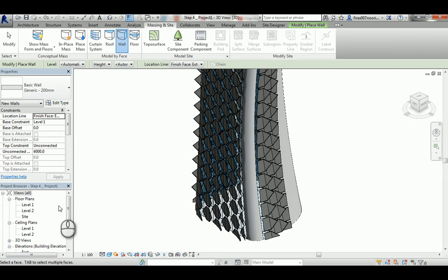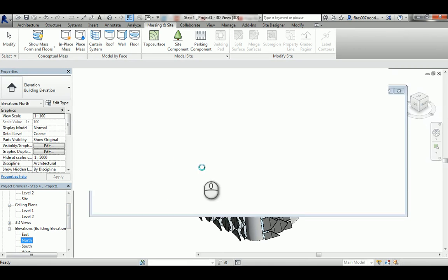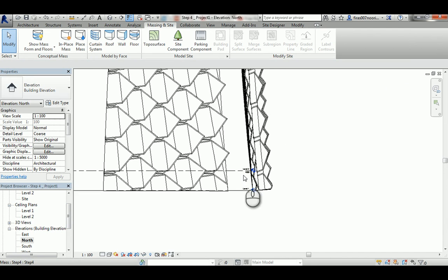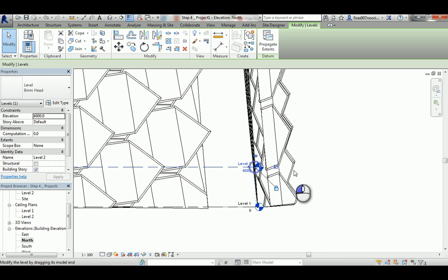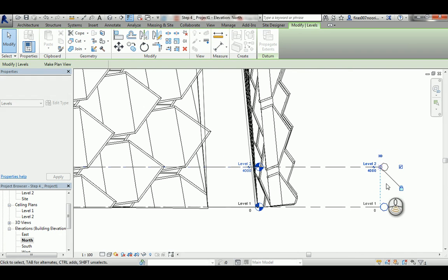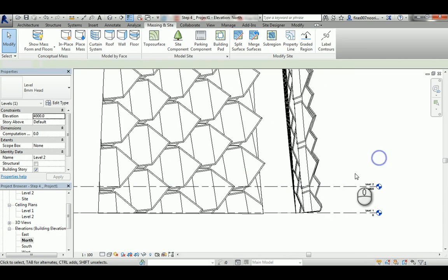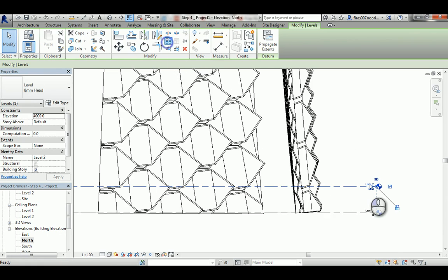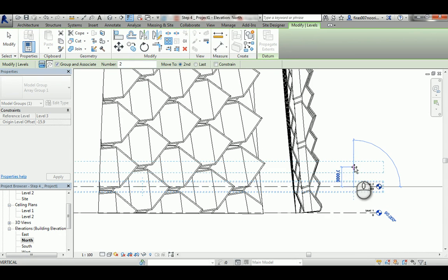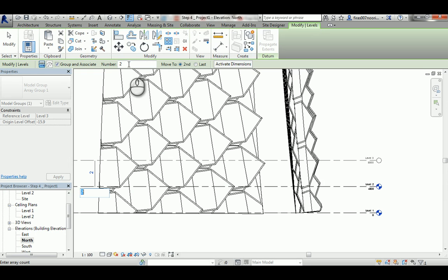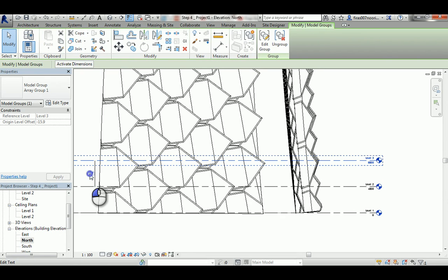so I'm not going to change anything in that. I'm going to go here to the north elevation, and in the north elevation I'm going to drag that out from both sides so it doesn't overlap with the geometry, and then you can select and hit Array, and I'm going to push that up, let's say 4, and instead of 2 let's go 40, actually 25, and I think I have to change that in here.